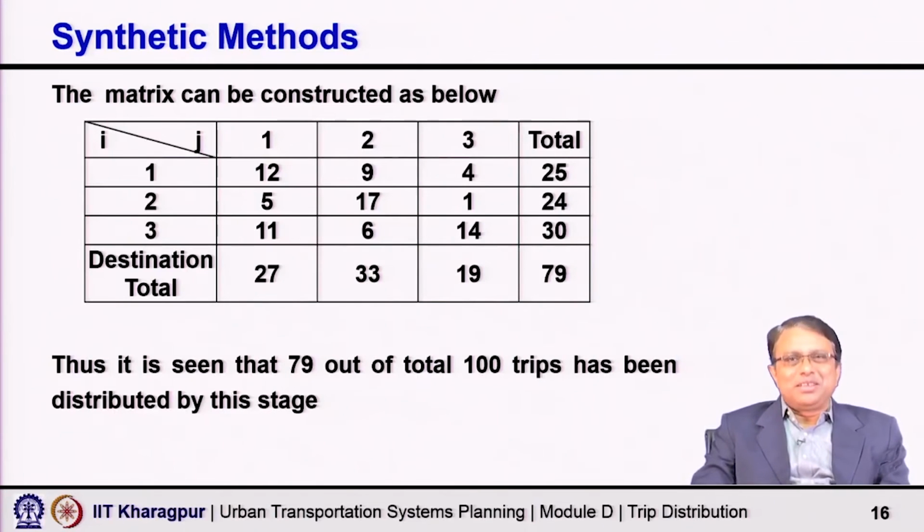You remember the singly constrained gravity model, when we took the production constraint models, the attractions were not matching. So, what did we do? We wanted this attraction to be this, when we targeted this, we got this. And in that same example, you want 80, when you target 80, you get 70.